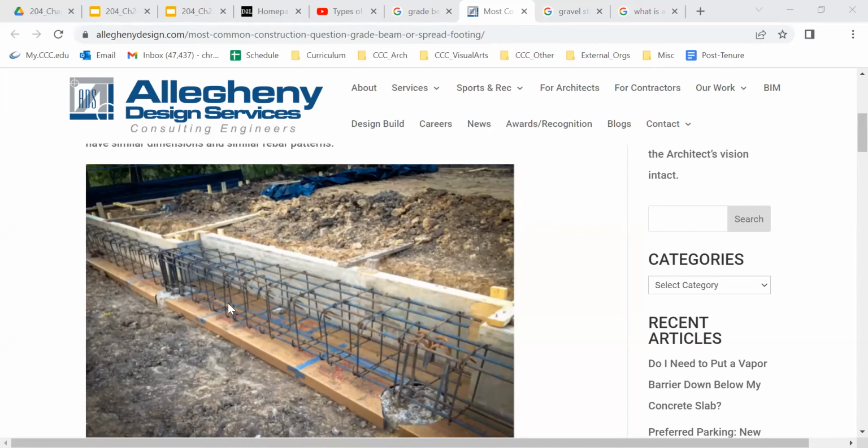Basically, our grade beam is going to stretch, and you can see it in this image here. There's a pier right here and a pier right here. Once the concrete is formed, the load path will go from the grade beam to those two piers, and it will not bear any weight on the materials below here. So it's just a temporary component that's placed during the curing process of the grade beam.